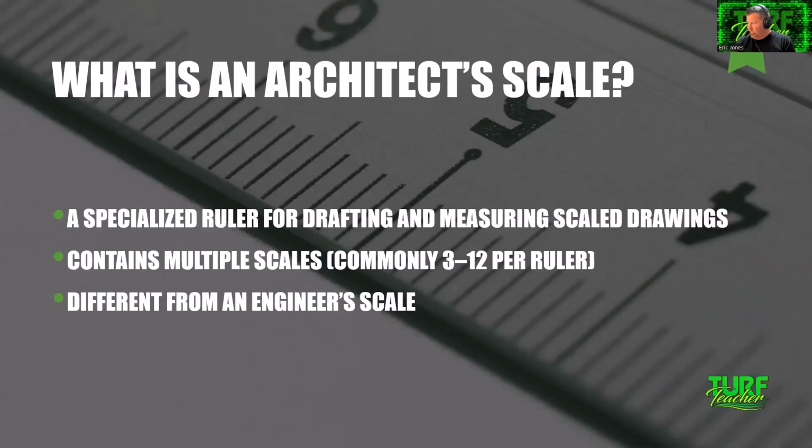So basically, if you were to use your good old tape measure, and I have a little red one right here, a little Milwaukee, that you need to keep in your design toolbox or your pencil pouch, whatever it is that you carry around your drafting tools. With the architect scale, if you've got 1/4 inch equals a foot, and we have a 1 inch, technically we have 4 feet per inch.